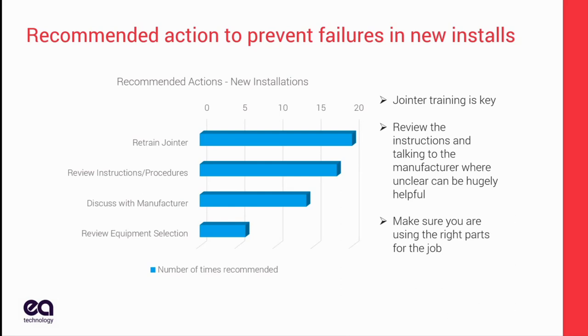Also look at the equipment selection. Classic example is hot shrink tubing. It takes a little bit more skill to do those terminations and get the tubing smooth and then do the torch work safely. You know, maybe you go to cold shrink. Doesn't mean it's that much easier, but it's less likely to be done wrong.